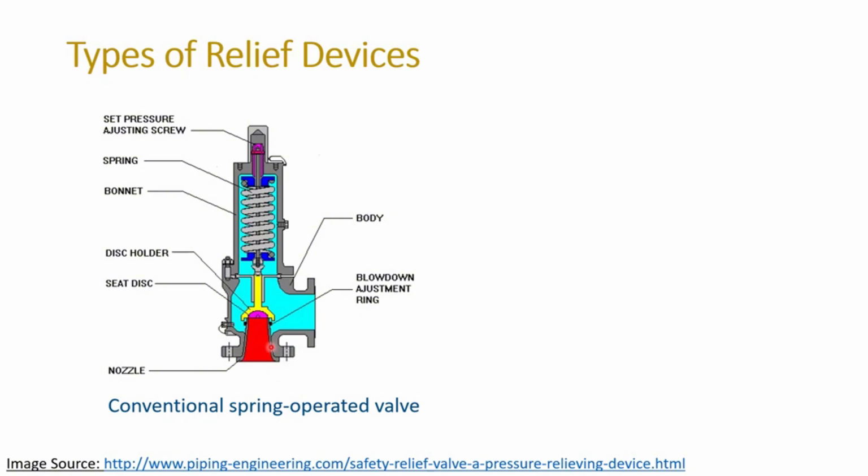The main components of the valve are the valve seat, shown here in pink, the valve plug, shown here in yellow, and the tension spring. The valve plug, here again in yellow, at the bottom of the tension spring is pressed against the valve seat by the tension in the spring, which keeps the valve closed. The spring tension can be used to modify the valve's set pressure.